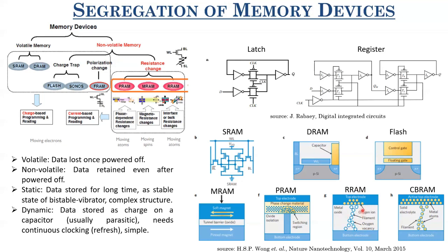So in soft breakdown, what happens? Oxygen vacancies and ions are separated. The ions go to the electrode, as these electrodes act like ion reservoirs, while the vacancies are distributed throughout this insulator. And the electrons can pass through these oxygen vacancies. So now you have something in the insulator connecting your top electrode and bottom electrode, through which the current can pass. So essentially your resistance reduces.